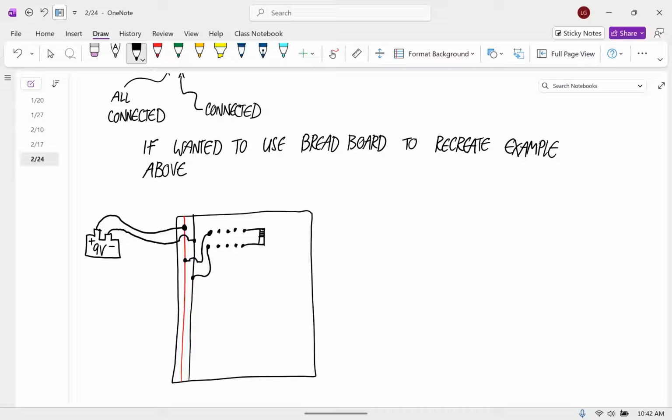Okay. So we'll talk about that all more later. I don't know from which angle it is. From which end? Yeah, it doesn't matter with resistors. They're the same in either direction. Oh, I gotcha. So you can see the side that they're closer to is the start. You know how I always draw them all close to one of these 2 terminals. That means that's the side that you would start looking at. So from here it would be brown, black, brown.